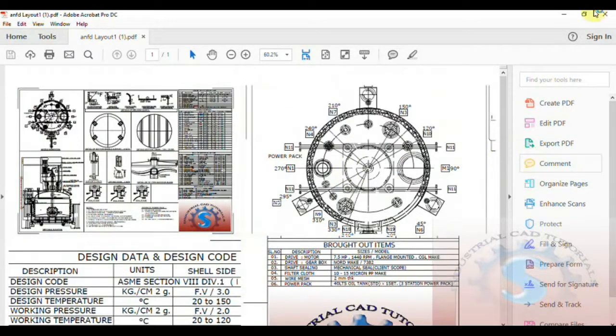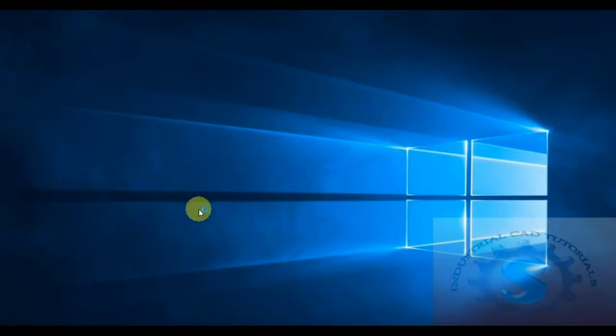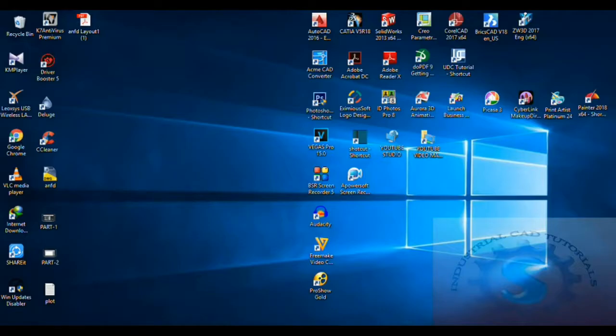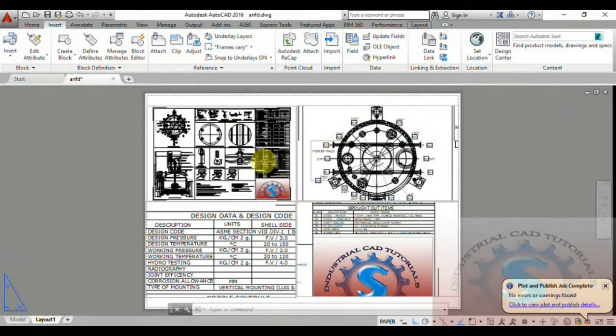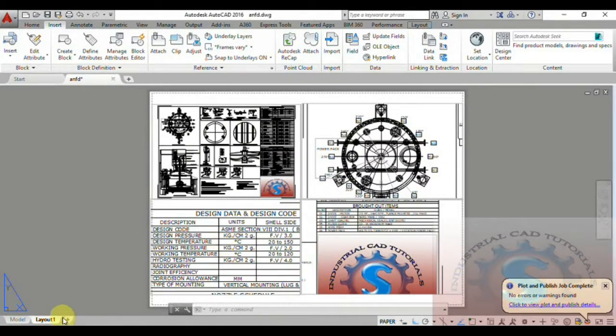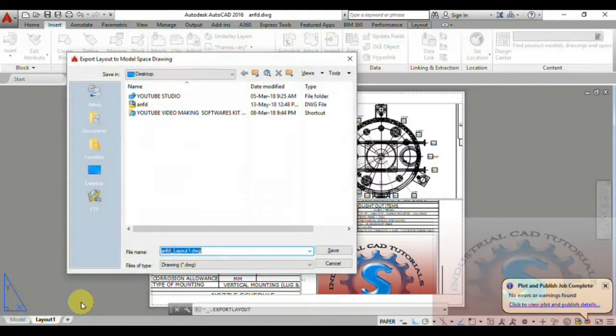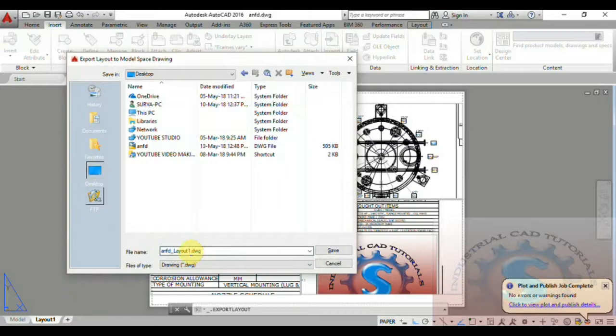By using the model you can adjust that, and not only in the model layout, you can also adjust the drawing in the layout by using MView, the page space and the miscellaneous properties. You can use these 3 commands. You can prepare the drawing in less time by using the miscellaneous properties and the MView command.